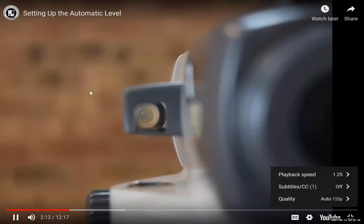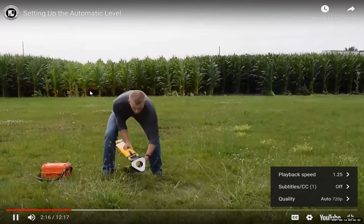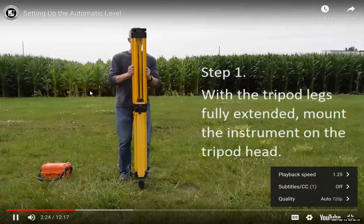Let's demonstrate the instrument setup process for an automatic level. First, with the tripod legs fully extended, mount the instrument on the tripod head. Many tripods use locking clamps to fix the leg lengths.